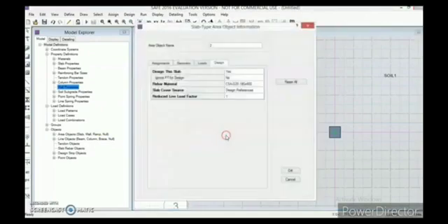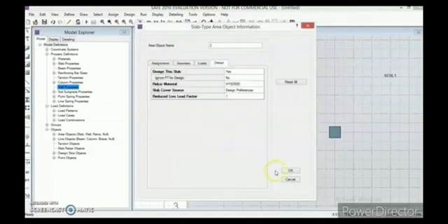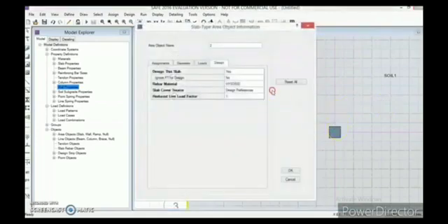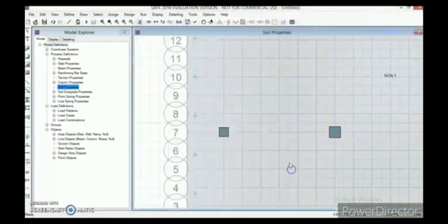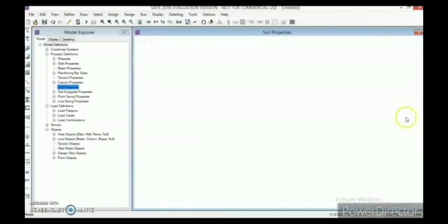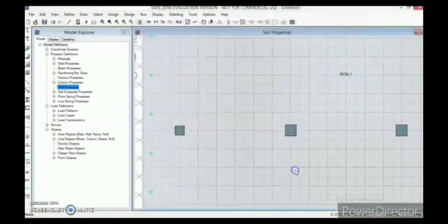So right click on the area and it is being displayed the rebar material as CSA. So we need to change it to HYSD 500 and click on OK. Click on OK again. So now you can check this property by right clicking. Yes, it's HYSD 500. Okay, now it's been assigned to all. You can check further taking other columns also, and please be careful that you are clicking inside the area, and it's HYSD 500. Fine.